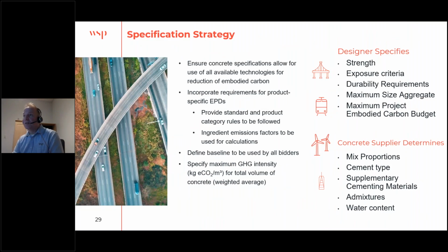And ensure that all of the specifications allow for all available technologies, provide standards and product category rules for EPDs that must be followed, define the baseline that is to be used by all bidders, and specify the maximum greenhouse gas intensity that is to be used for the total volume of concrete. So in essence, again, the designer specifies the strength, the exposure class, durability, maximum product embodied carbon budget, and leaves it to the contractor, the concrete supplier, the materials engineers to determine the mix proportions, the types of cements, et cetera, that will achieve those specified requirements.